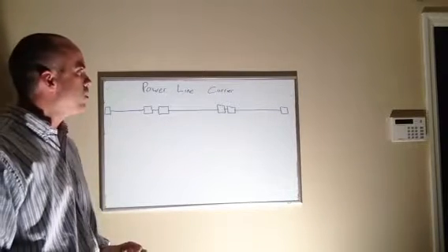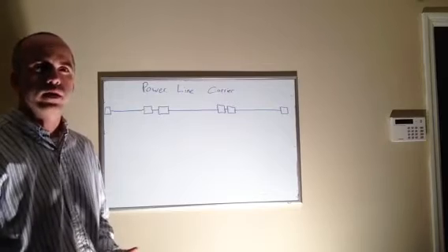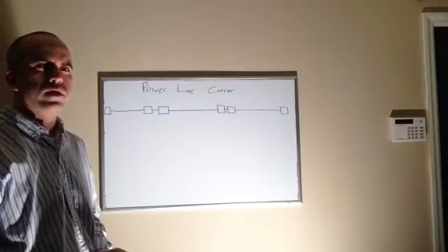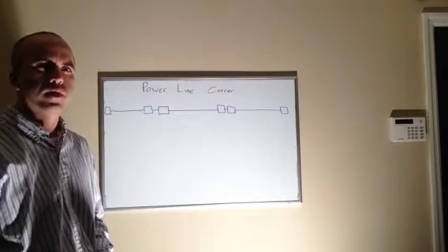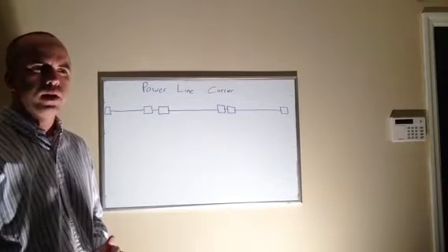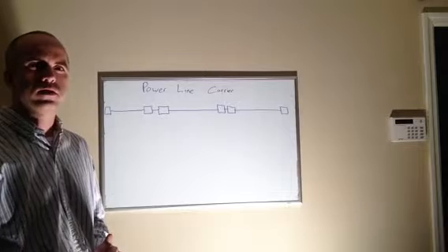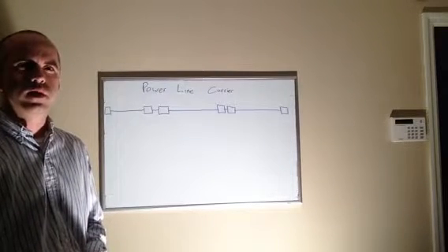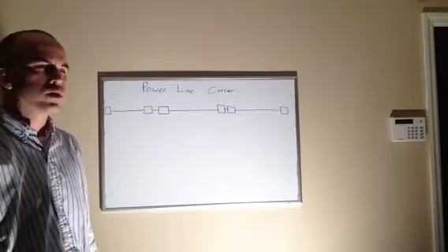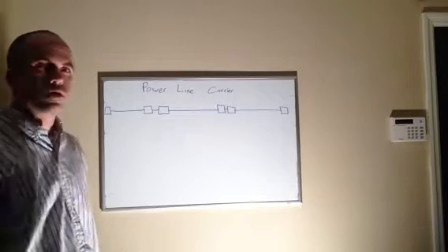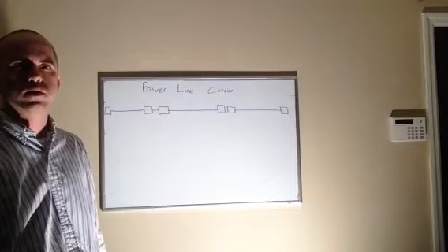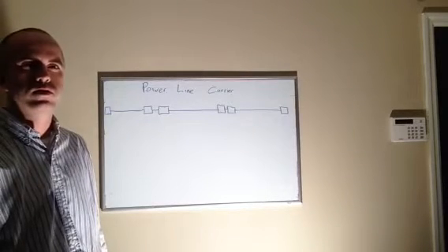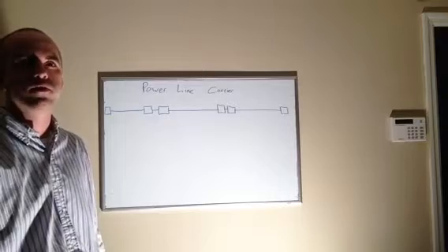The first thing I want to talk about is powerline carrier before we get into the POTT. Powerline carrier and POTT essentially accomplish the same thing. The main difference is that with powerline carrier, the communications is on the power line itself. With POTT, the communication is on fiber. So we're going to go through a scenario, put a fault on a line, see how the carrier works, and then we'll do the same scenario with POTT and see how they're similar and also how they're different.